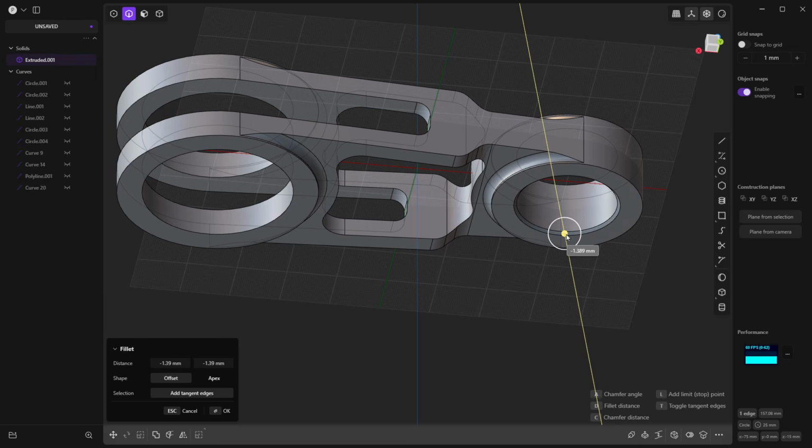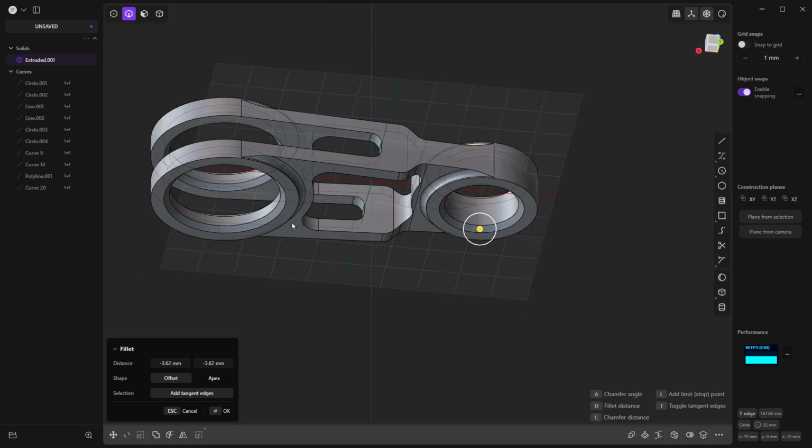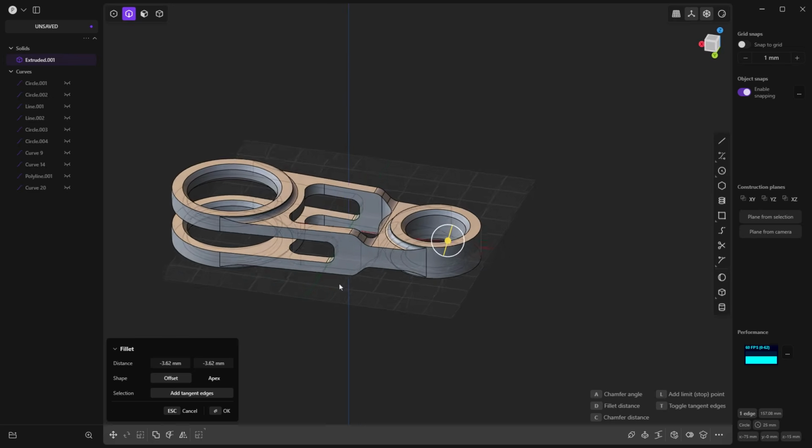Next, we're going to add a chamfer. With the fillet tool, when you select an edge, if you push it in, you'll get a chamfer. If you pull it out, you get a fillet. You'll have to play around with the direction. Sometimes it ends up being a little bit backwards, so you may just need to pull it both directions to make sure it's okay.